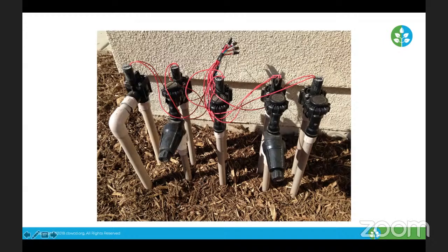That does not allow the water to be siphoned back into our system, because we don't want contamination from our irrigation system getting pulled into the municipal water system or even our homes, because of the pesticides and herbicides and things like that which typically get put on your landscape. I'm not saying everybody does that, but that's the idea behind having these irrigation valves for a residential setting.